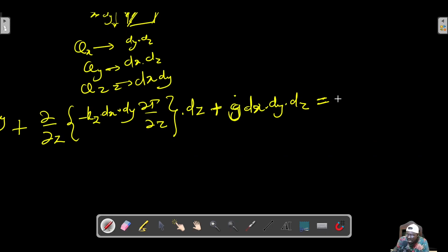And we said that will be the mass multiplied by the specific heat capacity at constant pressure times the partial derivative of the temperature field with respect to time. And we know the mass: that's the density multiplied by the volume, dx dy dz.